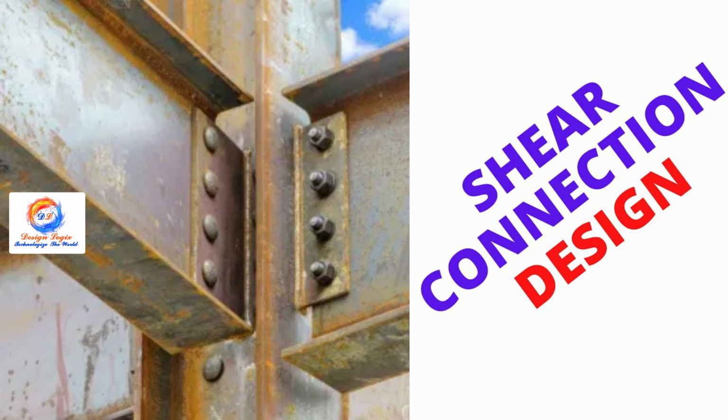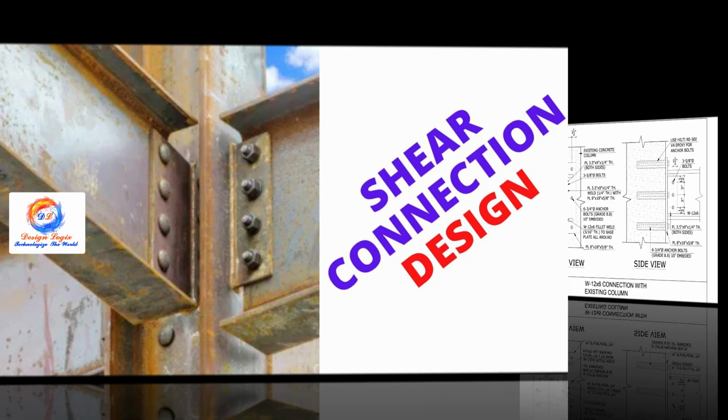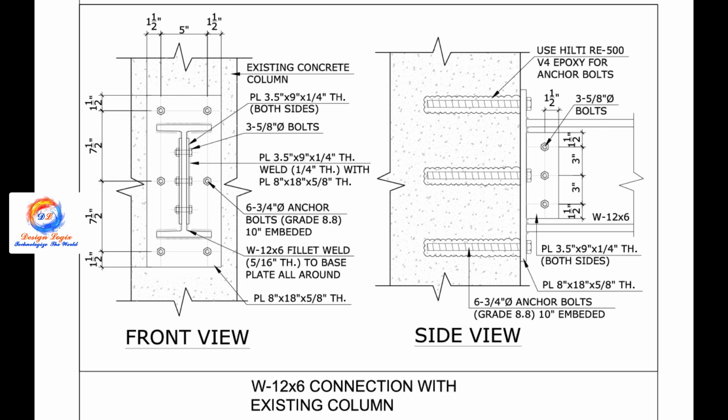First, let's talk about shear connections. As the name suggests, shear connections transfer only shear forces from one structural member to another. These connections allow free rotation at the node, which means that, in your structural analysis, this node behaves like a pin. Shear connections are widely used when connecting a new steel beam, such as a mild steel MS beam, to an existing column or another beam.